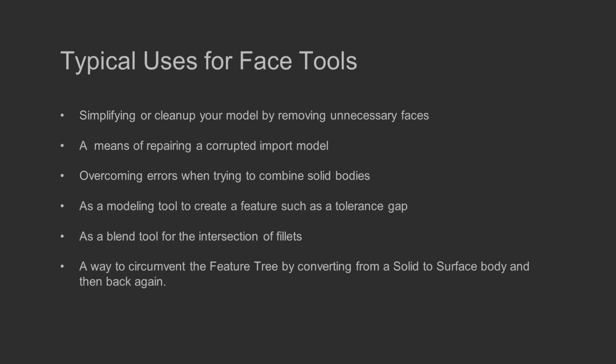It's obviously very useful for when you get imported models that come in and they don't come in quite right, even when you use import diagnostics and repair it. There are some areas where maybe you have to delete faces and rebuild them, or do a replace face to make the model correct.